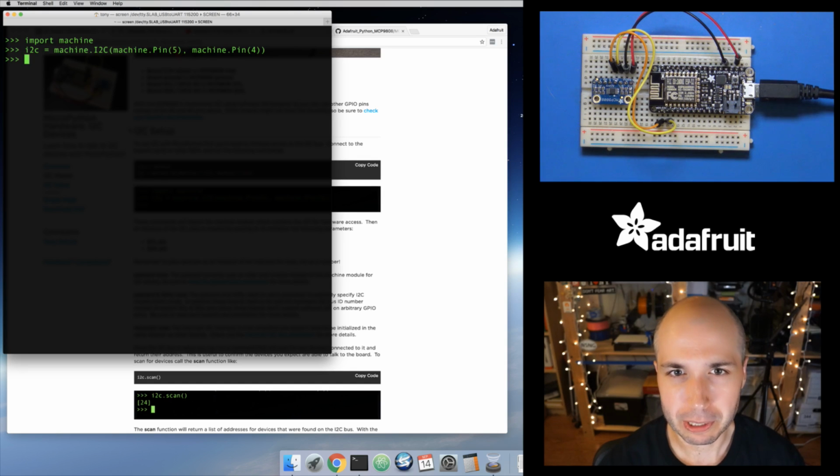For other boards like the Pi board and the YPi, they use a hardware I2C interface, where instead of passing in the GPIO pins, you pass in the number of the interface to use. So look at your board documentation. Usually you'll use interface 0 or 1, just because most boards have only 1 or 2 I2C interfaces. One thing to note too is that for those boards, when you do use a hardware I2C interface, you usually have to use a specific set of pins.